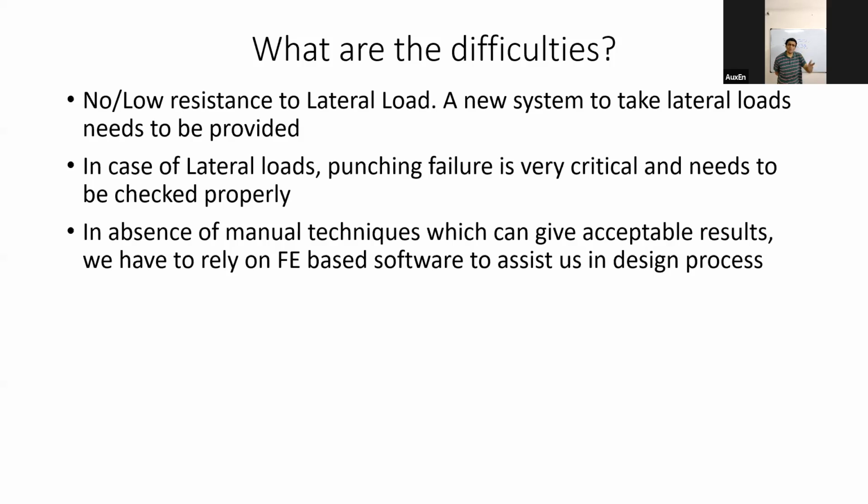Because for gravity loads, we understand the issues and we design accordingly. But the lateral load issues, we do not understand properly. And the shear wall locations, or the forces on shear walls that we calculate, are not done with a proper understanding. And we commit lots of design errors when we are providing a flat slab system with shear walls.